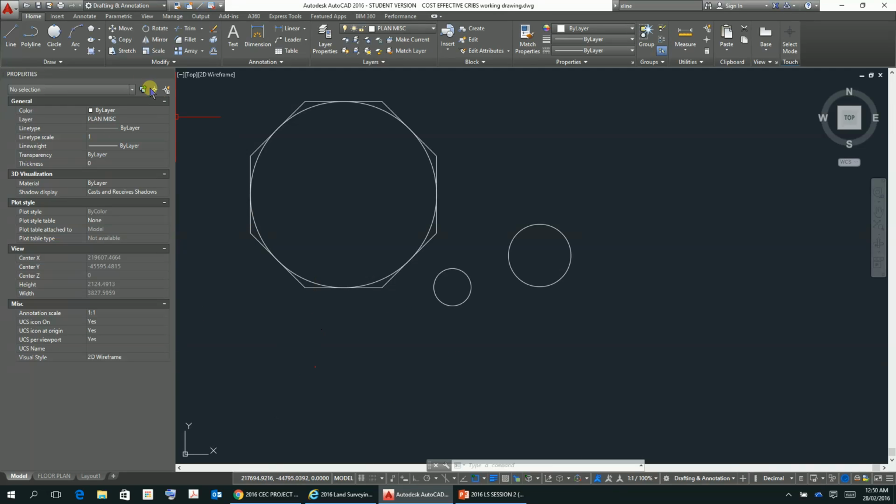So let's go here with a polygon. Number of sides, we'll just stay with 8. Let's specify the center of the polygon, which is going to be there, and inscribed, circumscribed. So let's go, oh, you can see that C was there, which is the one we seem to have there as the option.